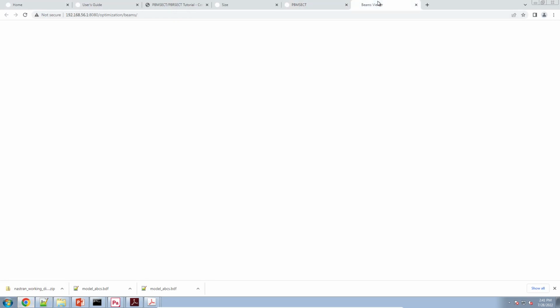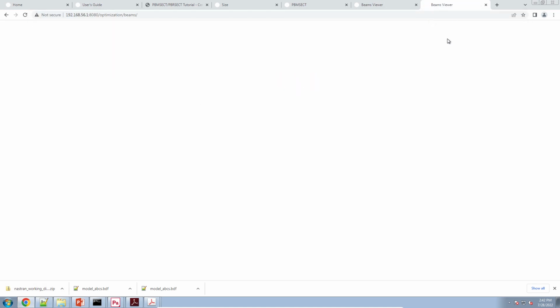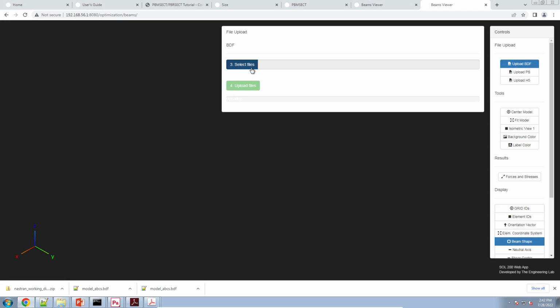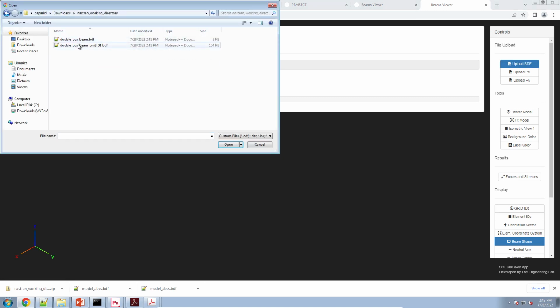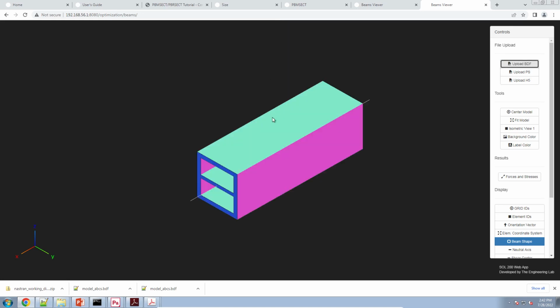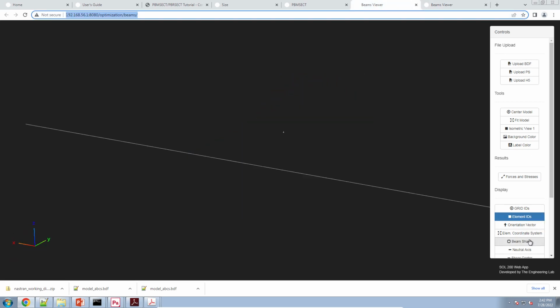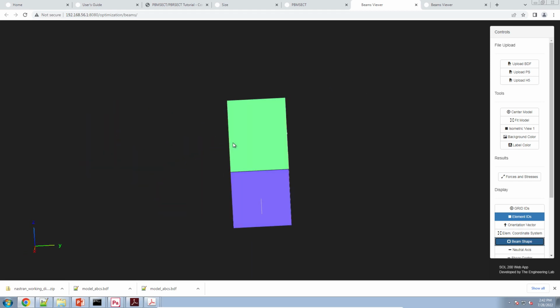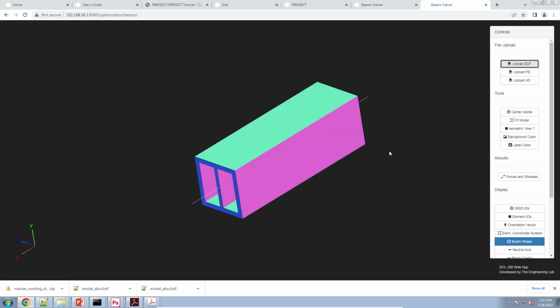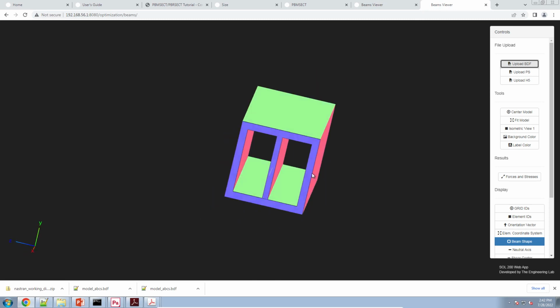If I go back to the beams viewer, let me actually show you what this CBEAM3 looks like with the new arbitrary beam cross section. So let's go ahead and select that updated file. And this is what the beam element looks like now. So remember, this is a CBEAM3. At the beginning, we started with the regular PBEAM3 entry, but now we've used the PBMSECT entry to define a cross-section composed of different composite plies.